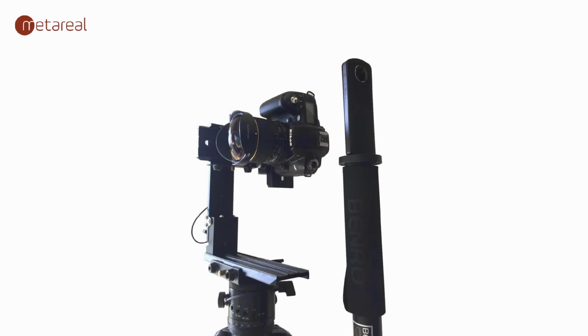This means that you need to shoot panoramas, equirectangular panoramas, as the input images for Stage. Now these can be either with any 360 camera, such as this Theta S here, or indeed with a DSLR that's fitted to a panorama bracket. It is very important, because we're doing 3D reconstruction, to make sure that the camera is properly aligned on the nodal point of the lens, so that the geometry of the resulting panoramas is very, very accurate.